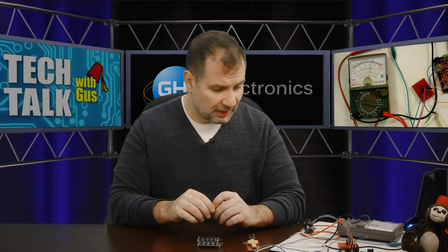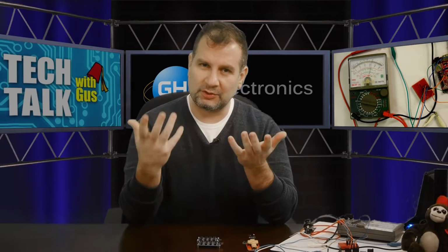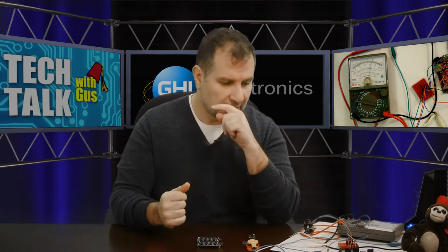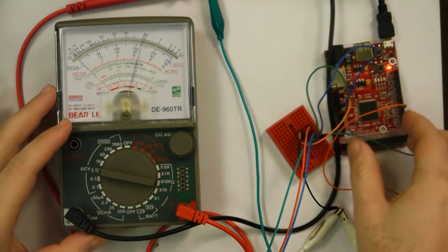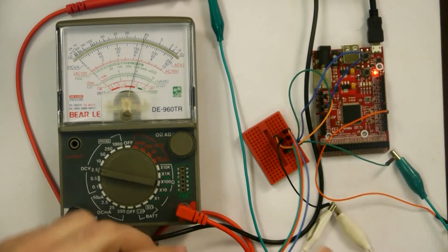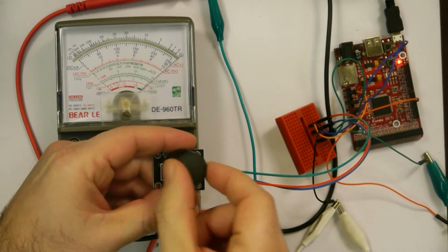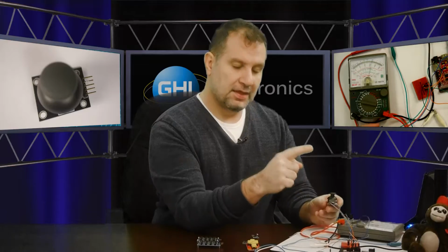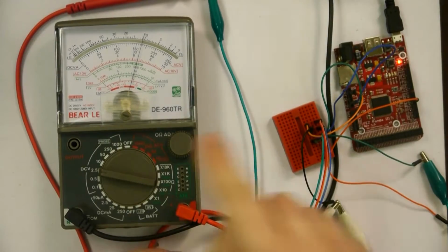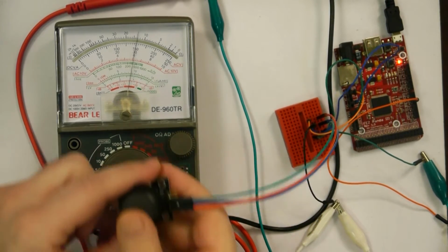I have several examples here. What I did to show you the analog values, so you can visualize them and get the idea across, is connect something. Let's say in this case I have a joystick, and a joystick outputs an analog value depending on where I move it. The output from the joystick is connected to the voltmeter, and I used an analog voltmeter, so it's easy for you to see what's going on.